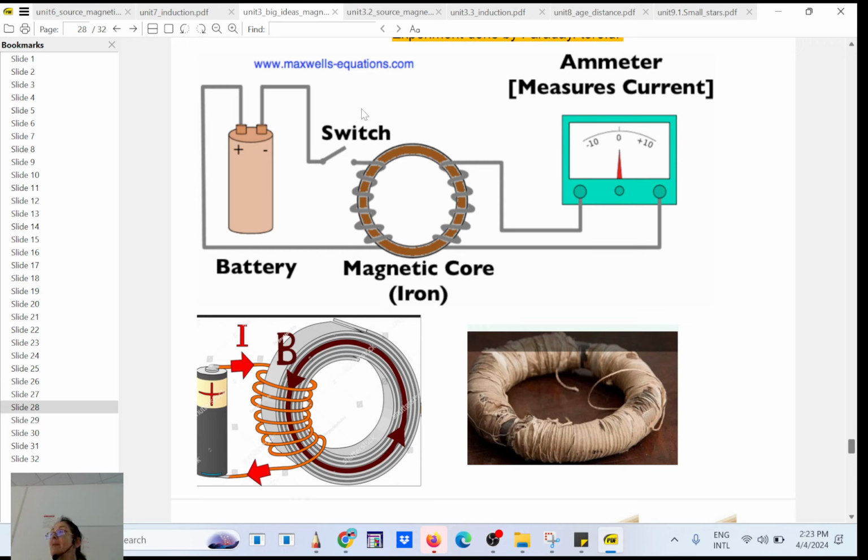So in his experiment, you see here, he had DC because Tesla was not around at the time. But when you close the switch, the magnetic field expands. So on the other side, you're going to see a change here, and then no more change. When you open the switch, the magnetic field is going to collapse, but it takes time for the magnetic field to collapse. So there will be a change here. The number of magnetic field lines will change. So you also see a change in the meter and EMF.